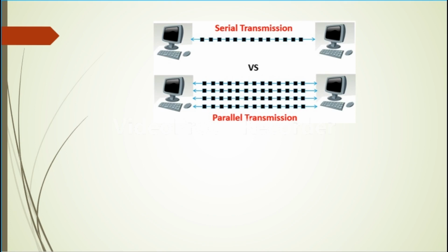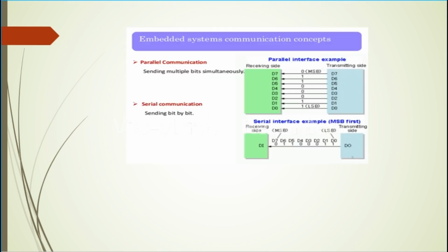Both of these systems have a unique way of operating, where the difference basically lies in the method of relaying those signals and the level of connectivity that they would require. In serial communication, data flows from one device to another in a bitwise manner, which means that one bit flows at one clock pulse. Like here, 8 bits are transferred at a time, having a start and a stop bit. Notice you just have one transmitter and one receiver in this case. But in case of parallel, you have more than one transmitter and more than one receiver.